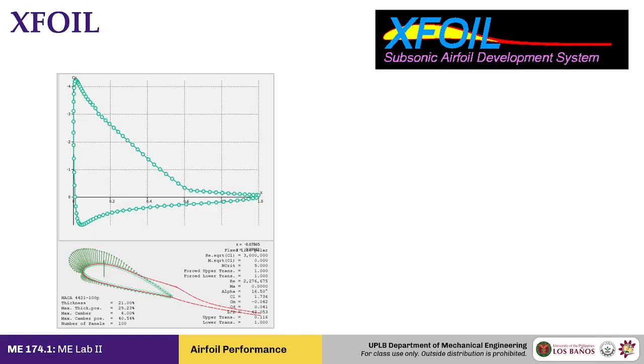It kind of looks something like this. So this is the OPPoint data in XFLR5. XFLR5 is kind of like QBlade, but it is more leaning towards fixed wing aircraft design. So this is the pressure distribution along a particular airfoil at a particular angle of attack. And what you notice here is that the y-axis is actually topsy-turvy. It is upside down. So this is a pressure distribution y-axis, but the positive direction is all negative.